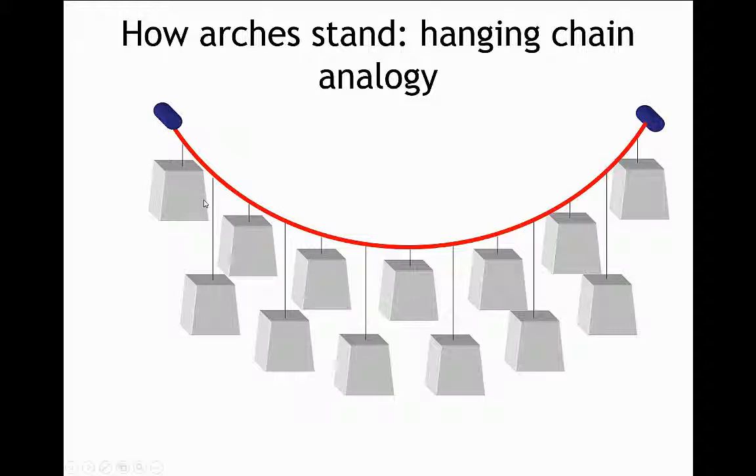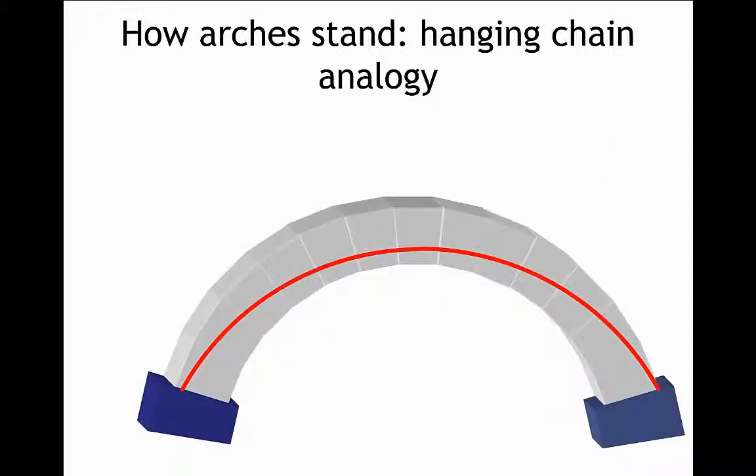In other words, if you take the voussoirs that you're going to use to form your masonry arch, suspend them from a weightless chain or cable, look at that profile, invert it, and find that you can fit that profile within the thickness of the masonry, then you've got an assurance that your arch is an appropriate shape to carry at least the self-weight of the masonry.